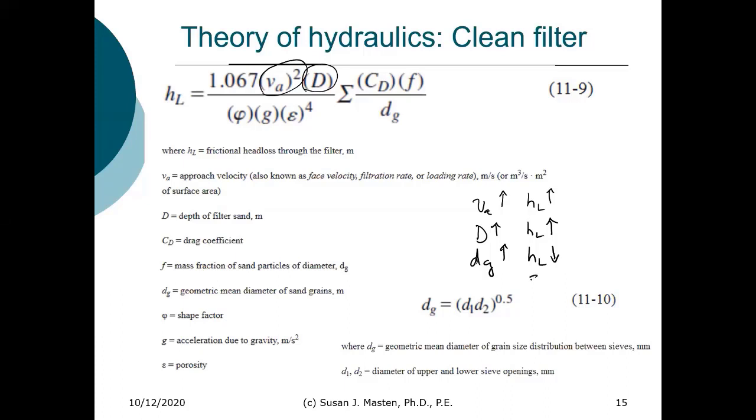As we increase porosity, we decrease head loss. And because this is to the fourth power, small changes in the porosity will have a large impact on head loss. I'm going to stop there.